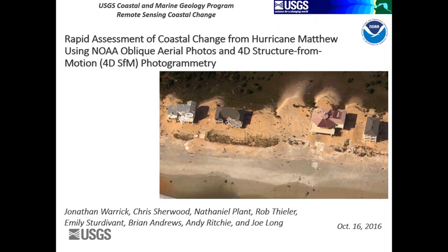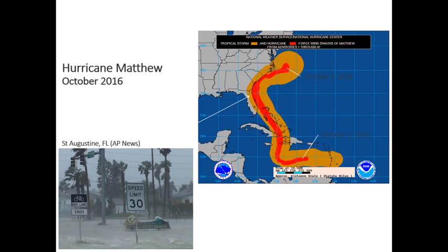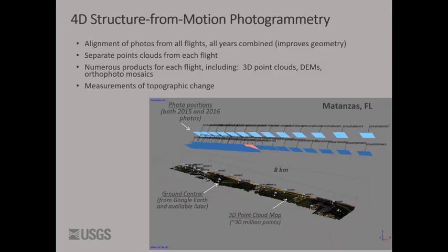And so here's the theory. There's pictures from one year, there's pictures from another year. Putting all those pictures together helps constrain the geometry of where the cameras had to be. These pictures were kind of roughly navigated. We kind of knew where they were with one GPS fix per picture, basically, and no idea about what the angle was. And we picked a bunch of control points using really old LiDARs, it turned out. The last LiDAR data that we had available was 2010. So we looked at roads and flat places and the tops of houses and used that as control points, basically all desktop control, nobody actually on the beach.